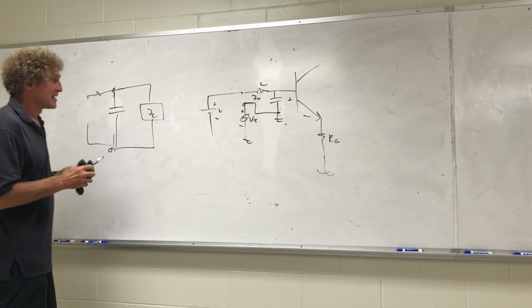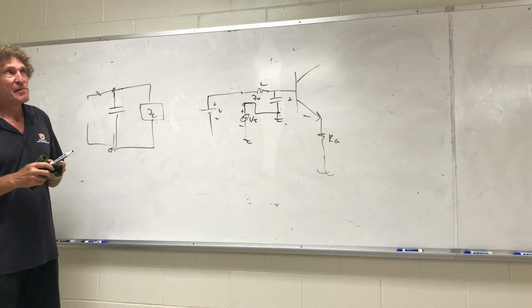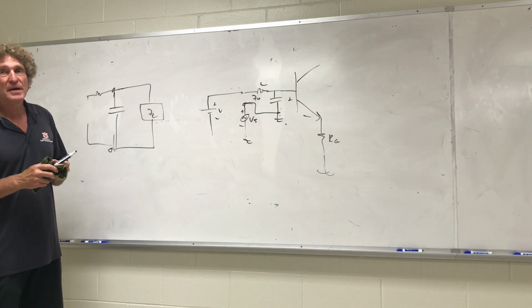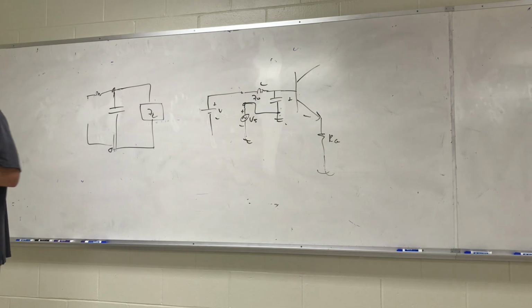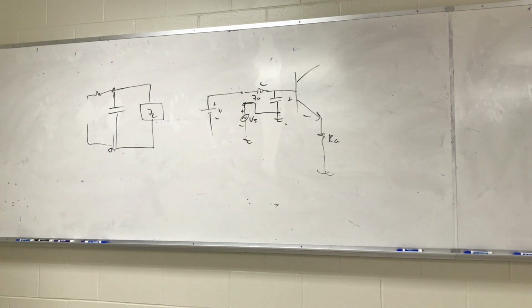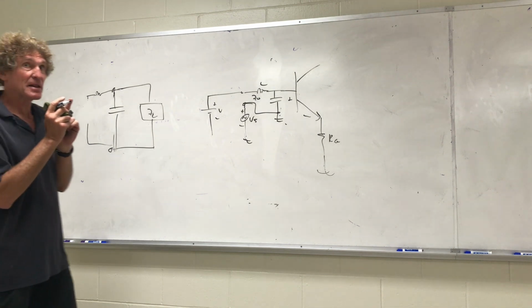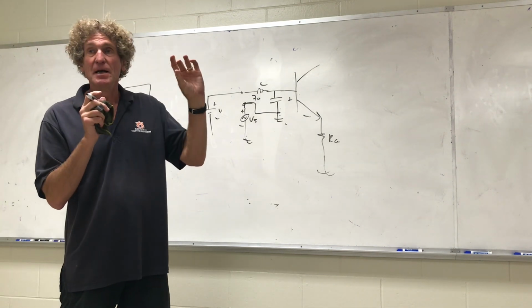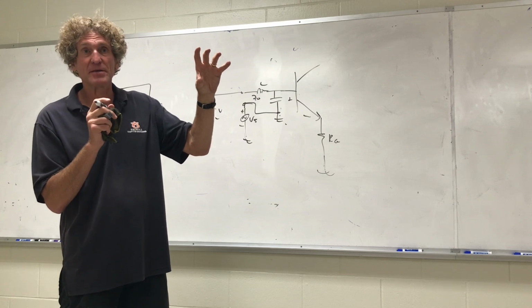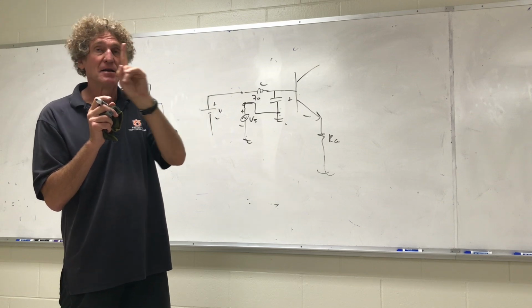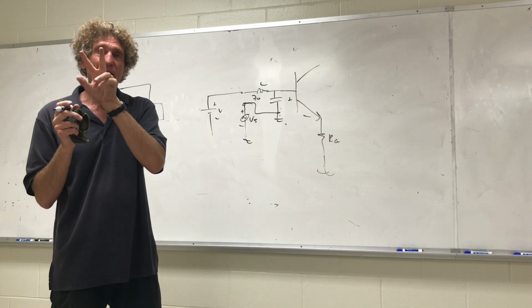Now, there are all sorts of tricks. There's the one thing bad about L-section matching, I must say this: it only works well at one frequency over a small bandwidth. Remember, as frequency changes, the characteristic impedance of the line doesn't change. Y'all with me on this? So then that L-section network doesn't look like it's impedance matching as soon as you get outside the center frequency and bandwidth.